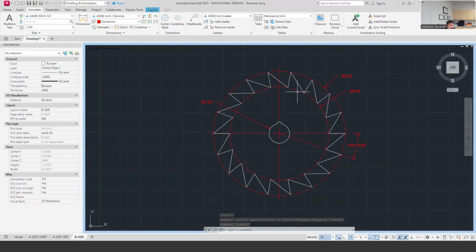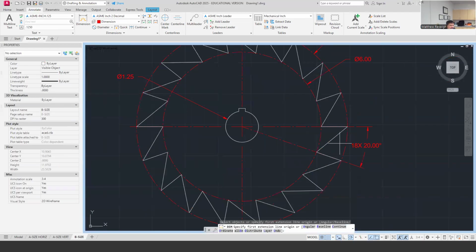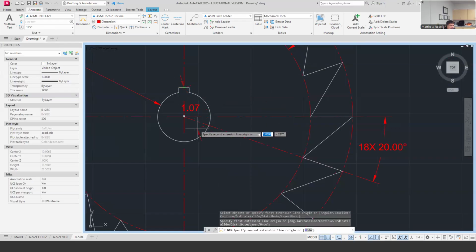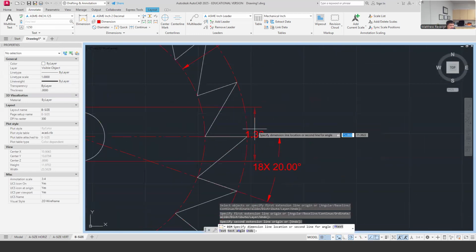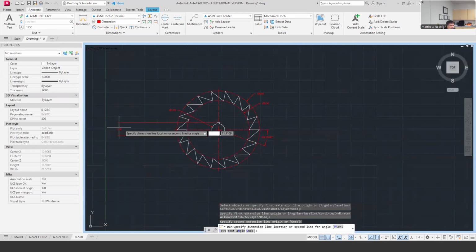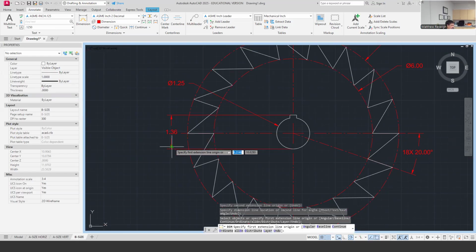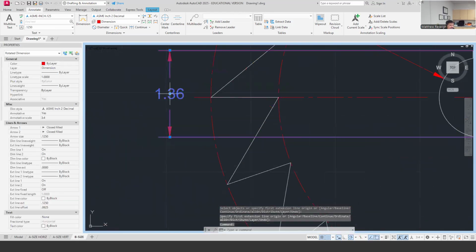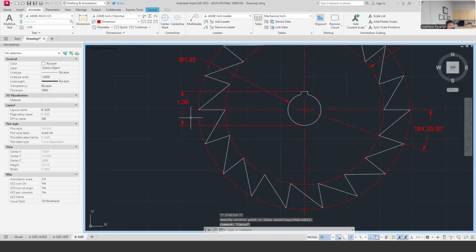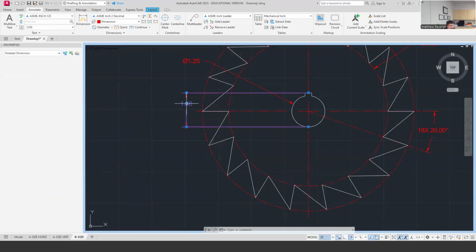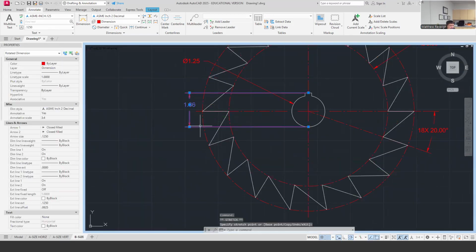Yeah, just select it first. So I've just got to add my linear dimensions here. I need this one, and ASME tells me this one is critical, so I'm going to drop that one out here. I could drop it to either side if I feel like that's going to conflict with my other. I only have a single view, so either side is good. I'm just making sure I clear the center mark more than actually following that 3/8 offset. I'm probably further away than 3/8.